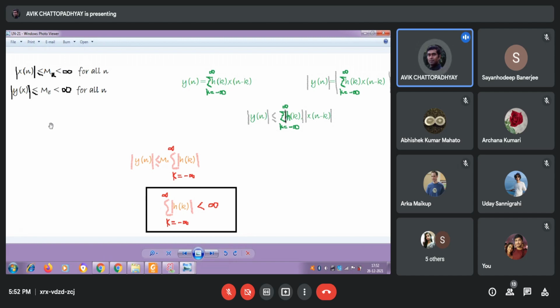That we know, we have already discussed. What I said the previous day, and what we discussed a little while ago, is the condition of causality in terms of the input and output, and how it is translated to the condition on the impulse response of the system: hn should be 0 for n less than 0. The condition was between the input and output. Now, how is it translated to a condition related to the impulse response of the system, from the perspective of causality.